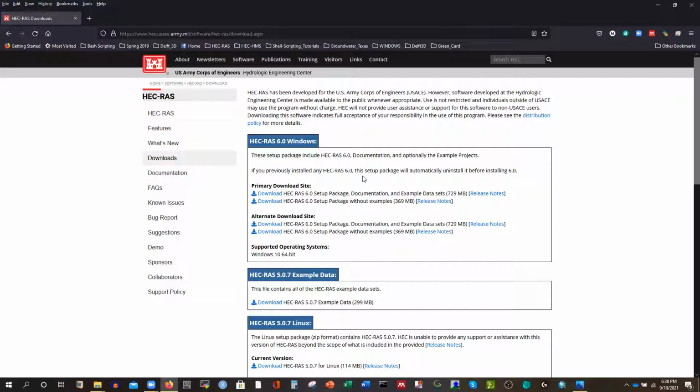So based on that, we will place the pier and we'll decide our span of the bridge, and then what will be the height of the lower chord of the bridge from the 100 year return period of a flood. So we'll analyze historical data, flow rate or discharge data, and also water level data to calculate the 100 year return period.